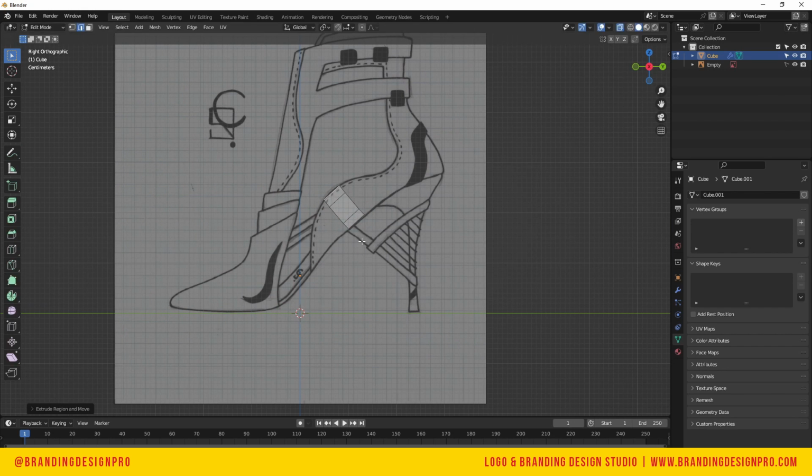Now we're going to go back to our object and then tab, select the edges, extrude down, extrude up, and then start to extrude the three sides out to work on our shape. So I'm just using E as a keyboard shortcut and selecting Shift to select more than one edge together, and S to scale. It's gonna be mostly those three keys that we're using to adjust the shapes like this, and then R to rotate the three edges